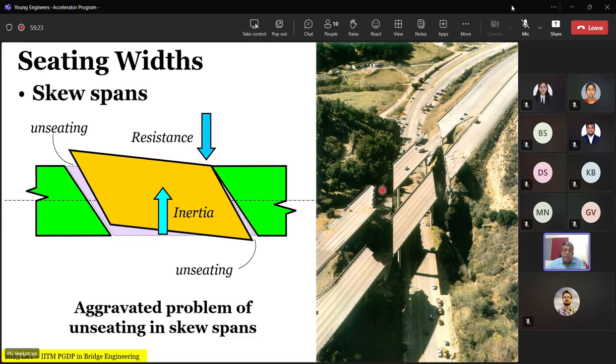What ended up having a problem was that when there was an earthquake and a lateral shaking of the bridge deck, when they provided the bearing articulation, that is the fully fixed, guided and things like that, the deformation all got accentuated in one place, it got unseated and the whole deck fell down. You can see the deck lying in the bottom.